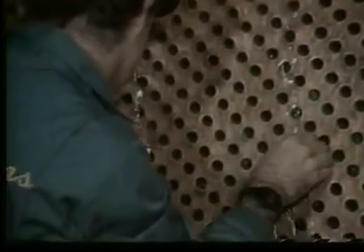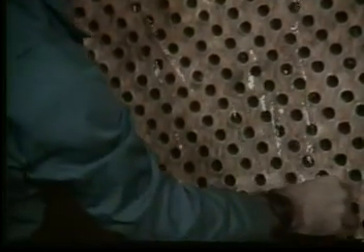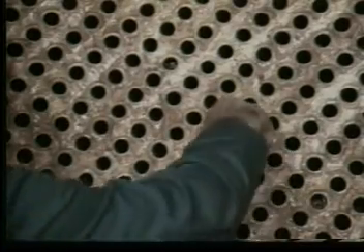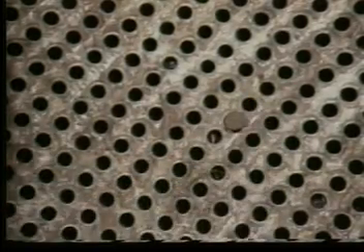To intensify the sound of air in leakage on the inlet side, seal off the outlet tube with plastic wrap. When the loudest area is found, scan around in a star pattern to ensure it is louder and of a different sound quality than the surrounding areas. Mark the loud tubes with cork plugs.